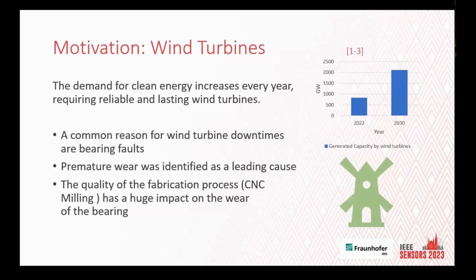The bearings are manufactured using CNC milling, and if the surface quality in the fabrication process does not meet the standard or the quality requirements, the bearing will fail prematurely, which leads to downtime of the wind turbine, which will lead to no energy produced by this wind. And as we can see, we will need more wind energy in the next years, meaning that the demand for those bearings will also increase.